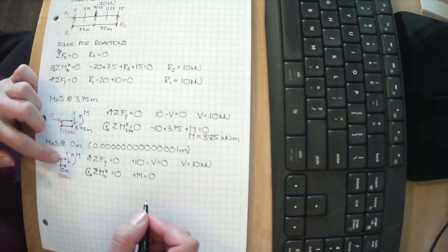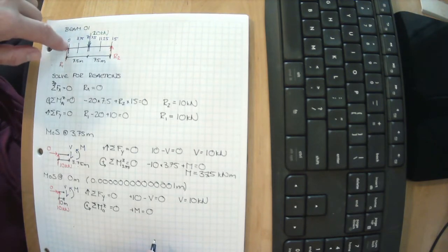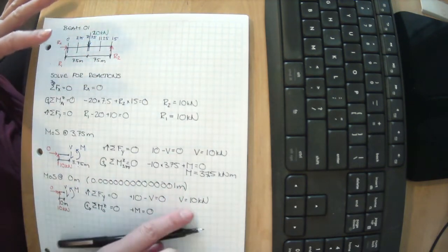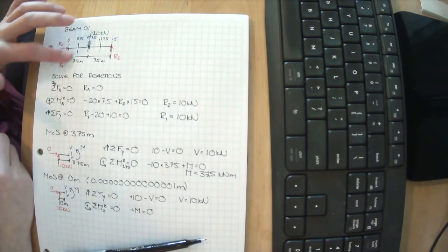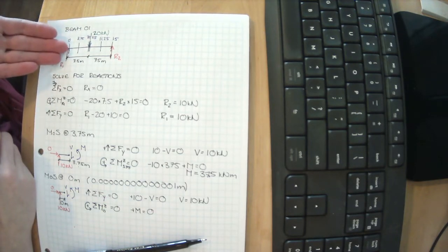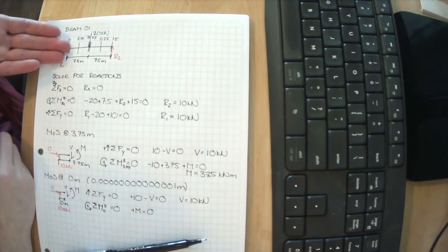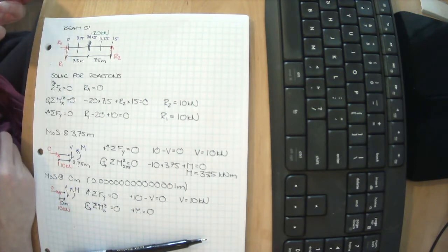So at this point right here on our beam, we have 10 kilonewtons of shear and no moment. This makes sense. Remember, this is a pinned roller condition. There is nowhere for the moment to go. We cannot accept moment right here. So it's a darn good thing there is no moment there. If there was moment there, we would have to have a reaction of some sort that could take moment. And remember, in steel, detailing a moment connection is really hard. We don't like to detail moment connections in steel unless we have to.